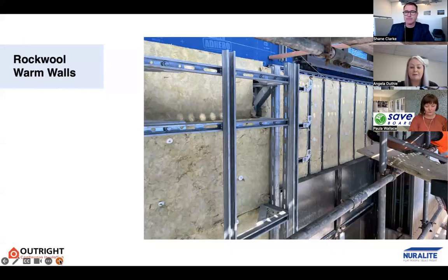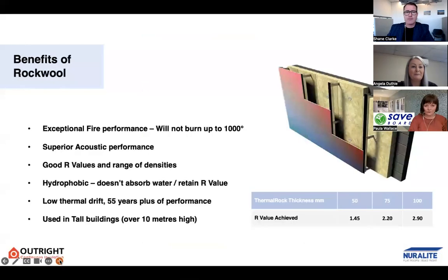So there's a number of iterations using multiple wall claddings, wrap layers, looking at your thermal values, whether you want it to be air or vapor tight, and then of course your structural options too. I'd also encourage people to look at their thermal and condensation modelling when they're looking at building up different wall programs.